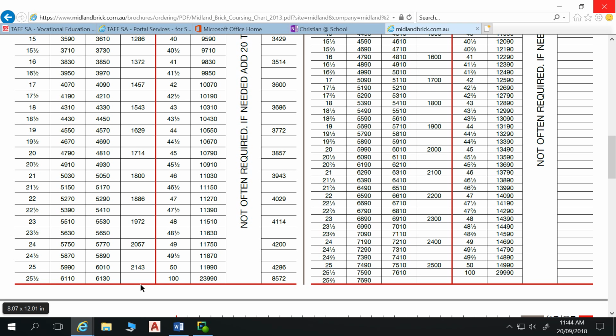Also, when I was doing detailing for a lot of repairs of buildings, I had to do detailing from a lot of photographs. So engineers would go measure stuff on site, but then a great deal of measurements they didn't take. I'd have to look at walls and count the bricks. You go, okay, that's how high that wall is, or that's how long this run of wall is, because you can count your bricks and go, oh, I've got 18 bricks, that wall is 4.3 meters long, or that opening is 4.33 meters wide. So that's how brickwork dimensions relate to a house.